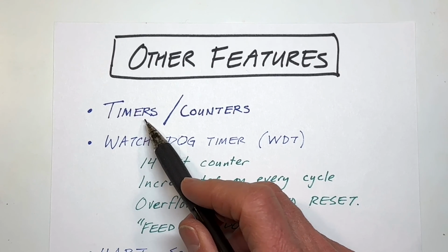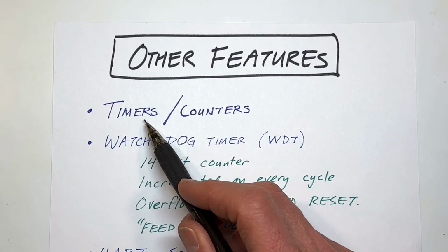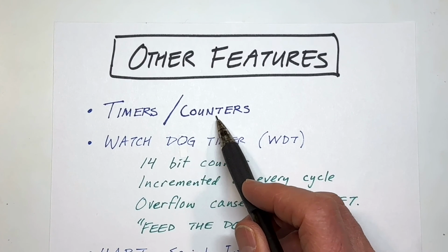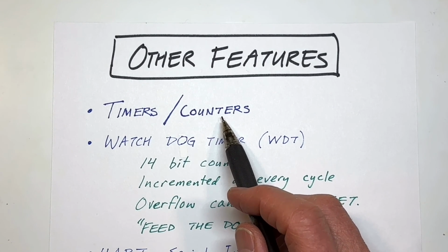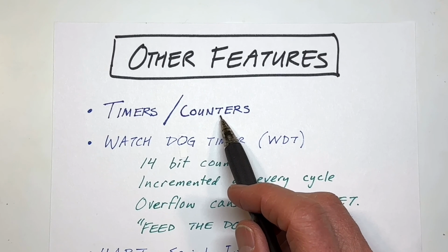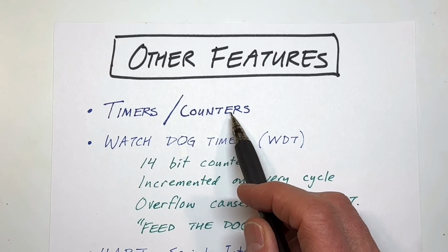These counters will advance automatically, and if they ever overflow, then an interrupt will be generated. They can also be used as counters, and here the idea is that an external pin is used to advance the integer, and so when it overflows, an interrupt will occur, but it's counting external events.